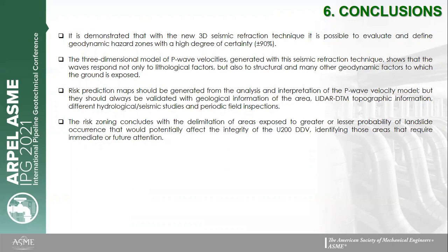Second, the three-dimensional model of P-wave velocities generated with the seismic refraction technique shows that the waves respond not only to lithological factors, but also to structural and many other geodynamic factors to which the ground is exposed.